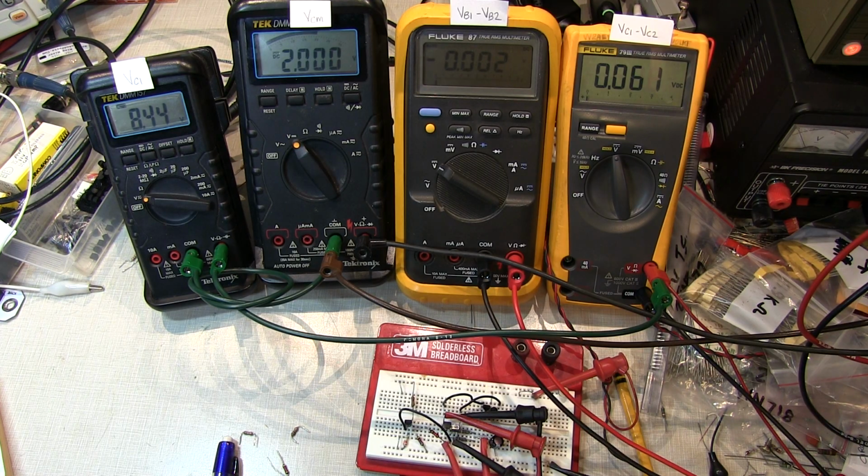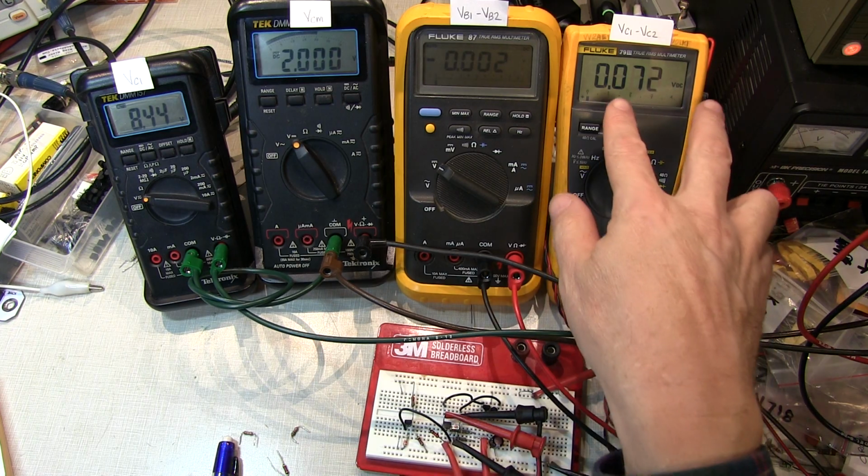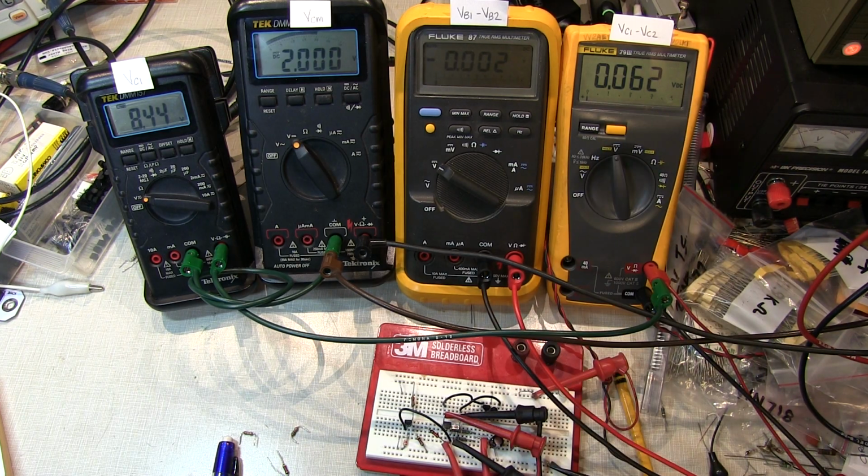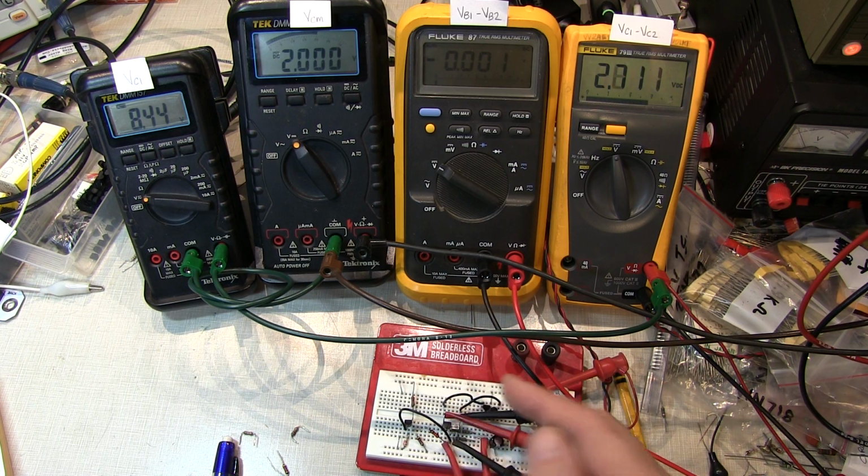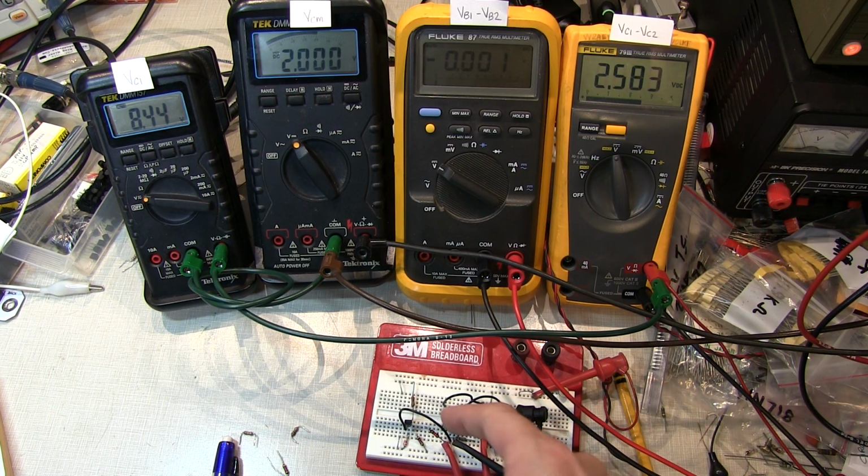But remember when we first started off, I put my finger on one of the transistors to change its temperature, and we saw a few hundred millivolt change at the input difference. Let's look at the same thing now. I put my finger on one of the transistors, and we're very quickly ramping up to several volts of difference, just with that small temperature change from my finger. I go to the other transistor, and we can bring it back the other way. So we can see the gain is much, much higher now.